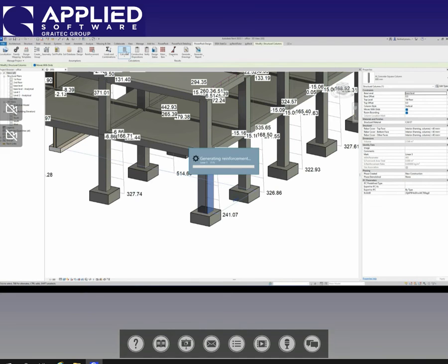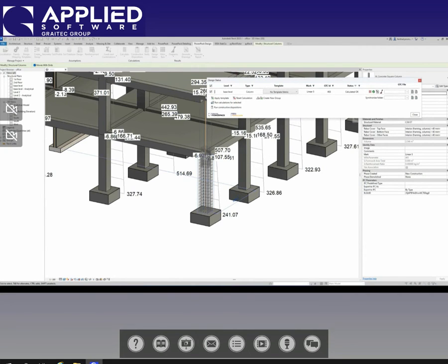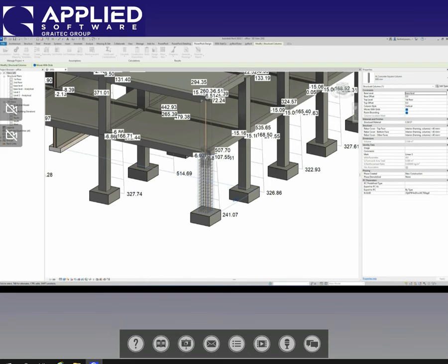Now in Revit, I am performing my concrete design. And as you see here, based on my forces coming from Advanced Design, our Power Pack will automatically generate all of my rebars. And the nice thing here is, again, you can also ask for reports from here. This check mark is showing me that the member is passing, so it's going to be enough, and the calculation is okay. So this is also a very nice tool in case you want to use it directly inside Revit.